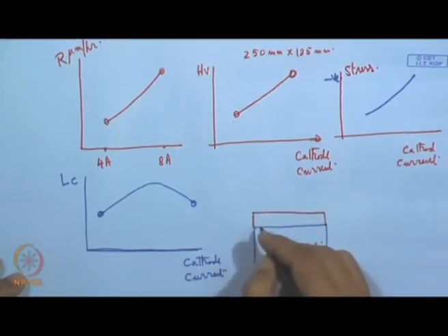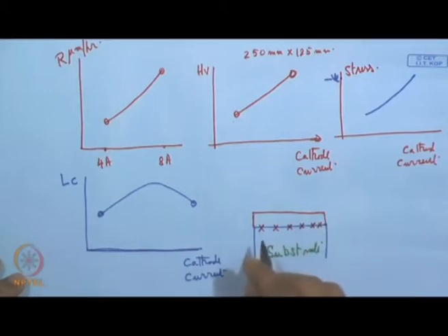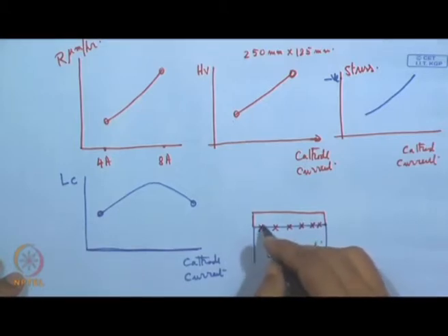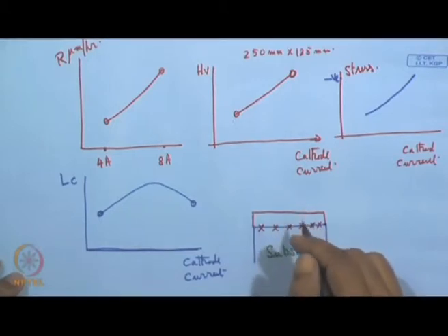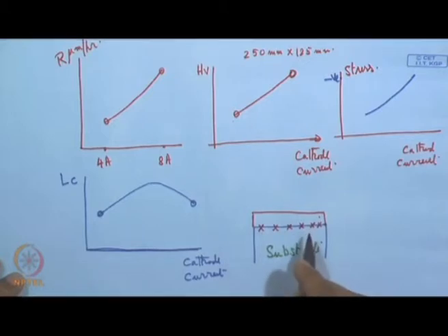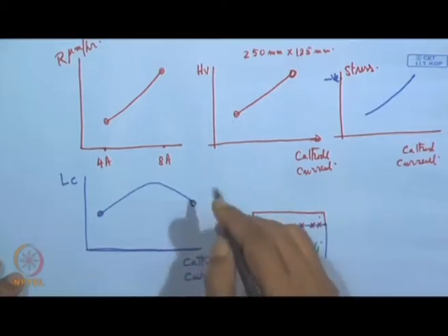So, we have to look at whether this high cathode current is actually detrimental for the building up of the interface. Now, this interface is developed at the very initial phase of sputtering, and at this moment if we have too much interdiffusion, which may lead to formation of a thick diffusion layer and too much reaction, then the characteristics of this reaction layer are quite different from that of the coating and substrate. Additionally, if it becomes a brittle phase, then that can also cause this loss of adhesion strength. As a result, we can see a falling tendency.